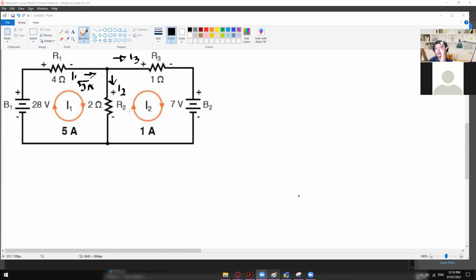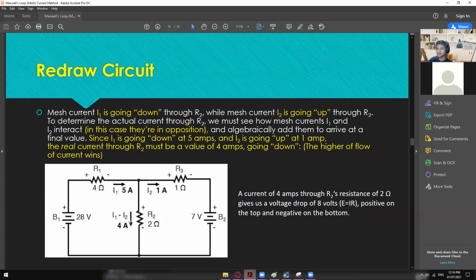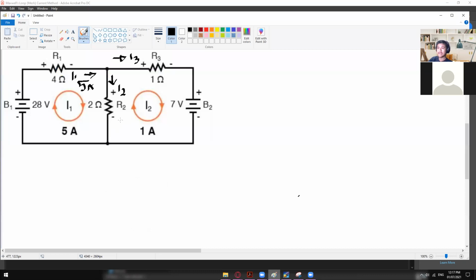Okay, so there is just a correction again. I've just noticed that the I2 was actually flowing in here, on the R3 part. And then the one that they assume as the I3 is the one that is flowing on the R2. Going in here, as you can see, I sub 2 is flowing on the R3. Since this is the third current, we could just say that this is the I1 minus I2 or the I3 itself. To avoid confusion, it will give us a value of, let's say, I3, which is 4 amps, and then I2, which is still I2, but the labeling is incorrect.